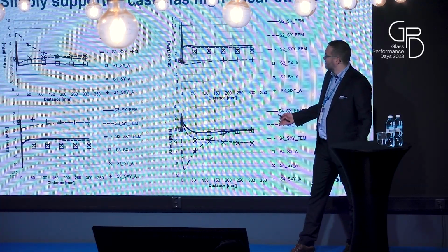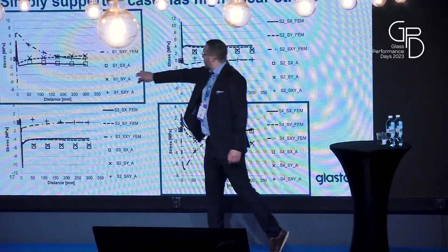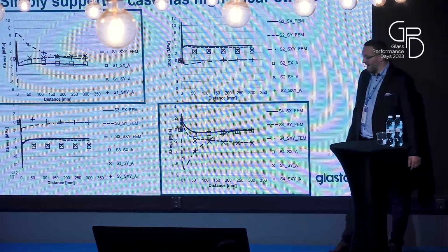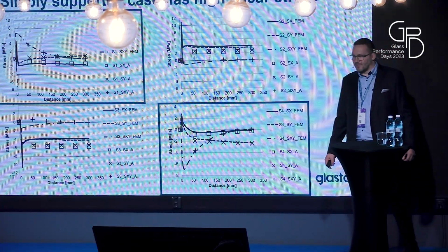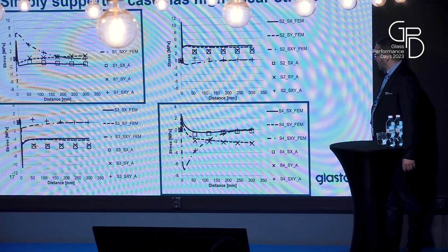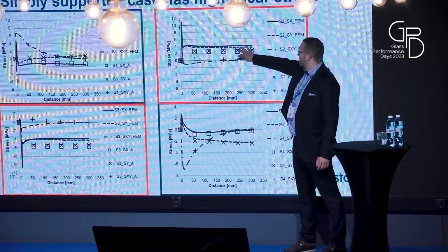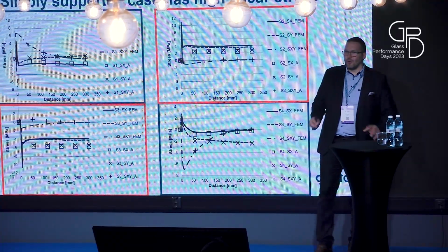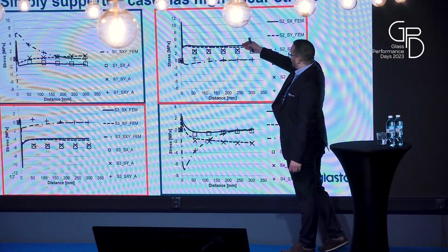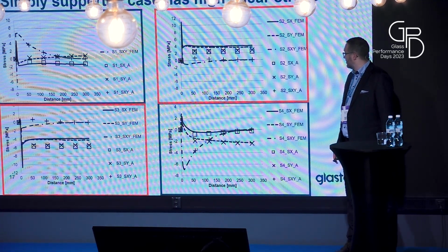If we look at results, outer surfaces on the cold side and hot side, dots are again analytical solutions, lines are finite element solutions. You can see that the dots and lines are matching quite well. But if we go to an internal surface, then most likely due to this gap, stresses are a little bit off for normal stresses between the analytical and finite element solutions.